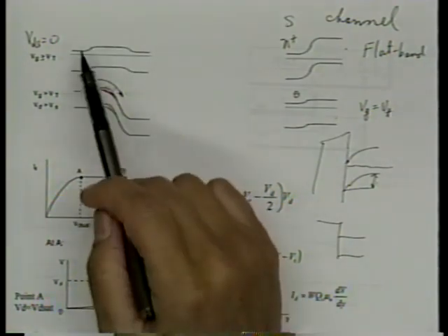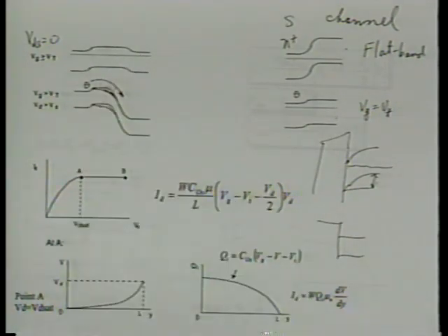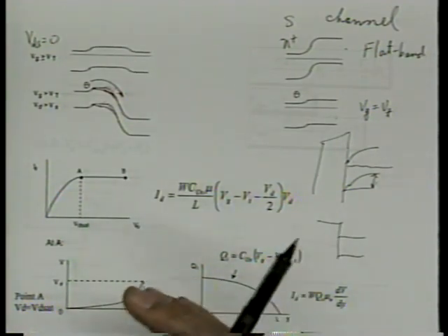So drawing the energy band diagram is also simple. There's one energy band diagram. Anytime you have current flow, we know we're not at equilibrium. When we're not at equilibrium, drawing the energy band diagram becomes somewhat of an iffy proposition. You almost have to do this iteratively, make some guess and see if it makes sense or not.